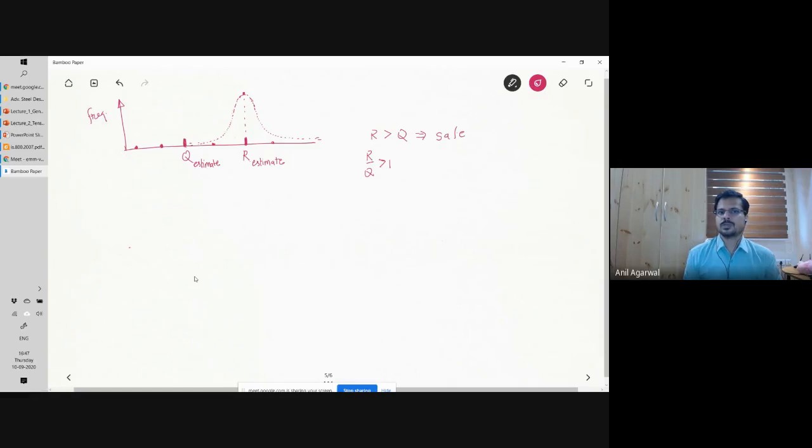You understand? So if I test a large number of such columns, for which I had estimated the capacity to be this particular value, the real capacities may be different. It may be here, it may be here, it may be here, but the chances of deviating away from this value will be smaller as you deviate more and more from here. Everybody agrees with this? You must have all seen these plots, right? Normal distribution. If my understanding of this behavior is correct, the highest probability will be in this area.